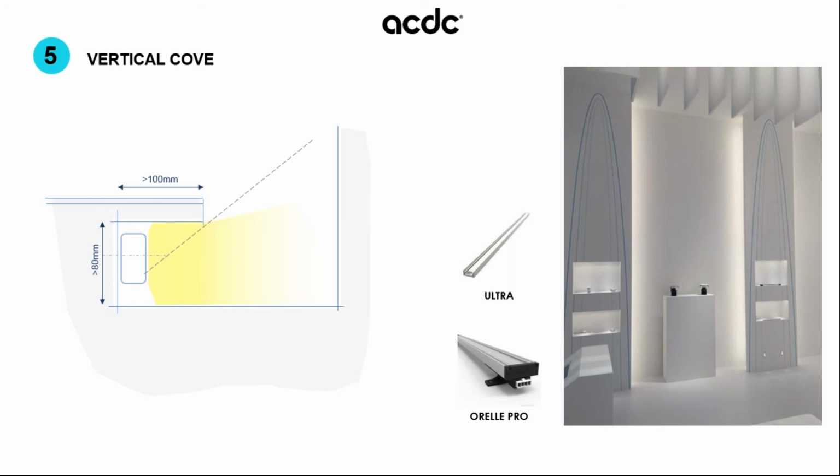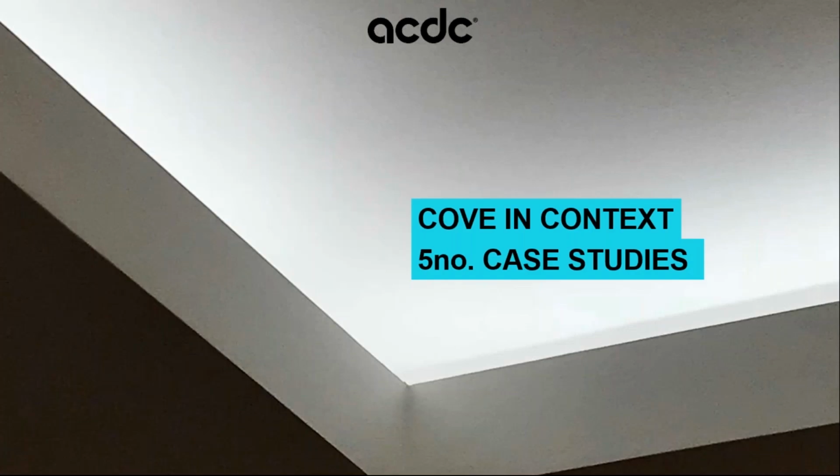Now this is probably more often used in a retail environment, maybe a changing room, where we've got that reflected, diffused light. We're using the surfaces, those matte surfaces. If it's matte white, happy days. Matte white, and we're bouncing the light off those surfaces so that we're modeling the face. We're modeling people when they're looking in the mirror, they're getting that diffused light. It's really, really important. So think about, again, color consistency, color rendering, the quality of how your luminaires go end to end to ensure there are no shadow gaps. It really should be a consistent lit effect.